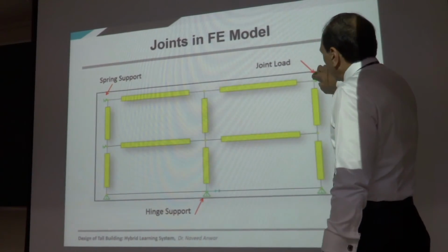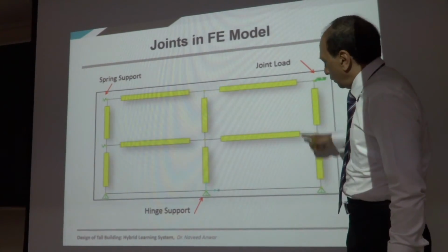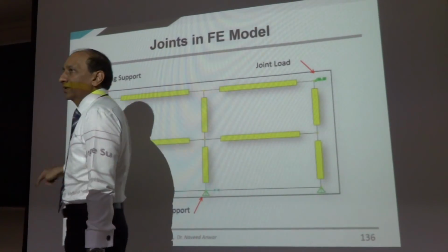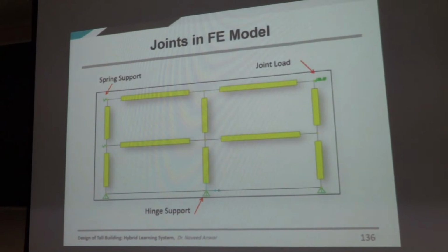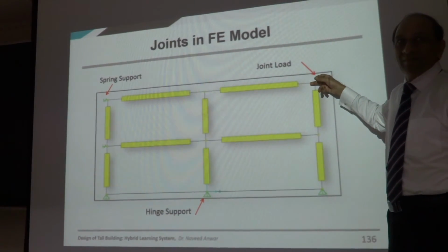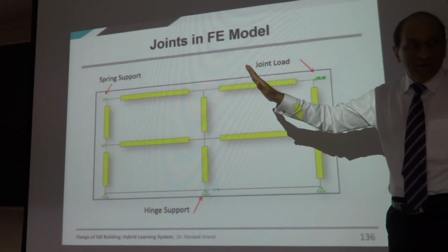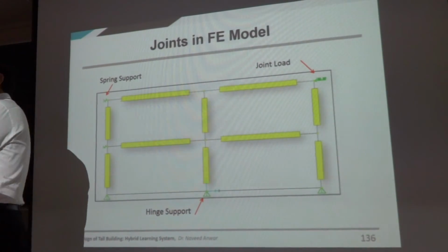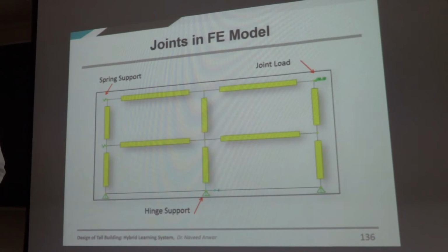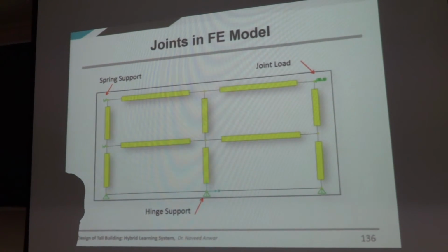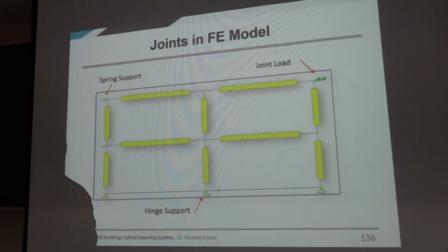So you can see the nodes give you the ability to apply the load, use the artificial boundaries, use the spring boundaries, and you can create the model depending on what you need. It could be that the soil is represented by load for the pressure that comes from the soil, or it could be that the soil is represented by a spring because the soil is supporting your structure. So which is happening? What is really going on? Is the soil pushing the structure as a load, or is the structure resting on the soil as a support?